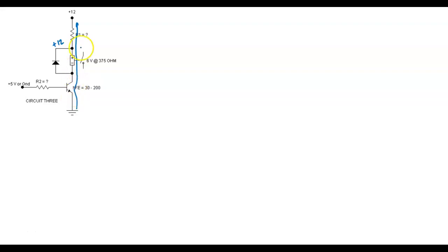When we turn the transistor off, this thing discharges, but when it discharges, this goes minus. That's why it's called a counter EMF. This goes minus, this goes plus. That forward biases the diode, and it lets that inductor discharge without going through my transistor. Right? You understand? If you don't have that, I guarantee you, it's going to blow your transistor out after a while.